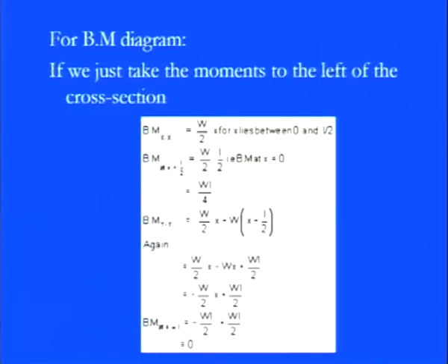So, you see here what we have at the starting point, that means the reactive point, since it is starting at the bending moment. So, we have a 0 value. If you move towards the middle where the point load is, we have the maximum, that is WL by 2, and then even if we go beyond the XX point, that means up to the YY point, then we have a different cross section.